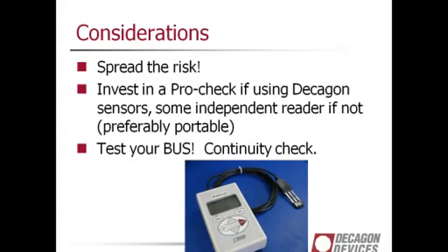Okay, so spread the risk is one recommendation I try to get across to customers that are going to be using SDI 12. Just because you can put 62 sensors in one port doesn't mean you have to. If you have 4 available ports, spread them to every port. It just minimizes the damage you will do if one sensor goes down.